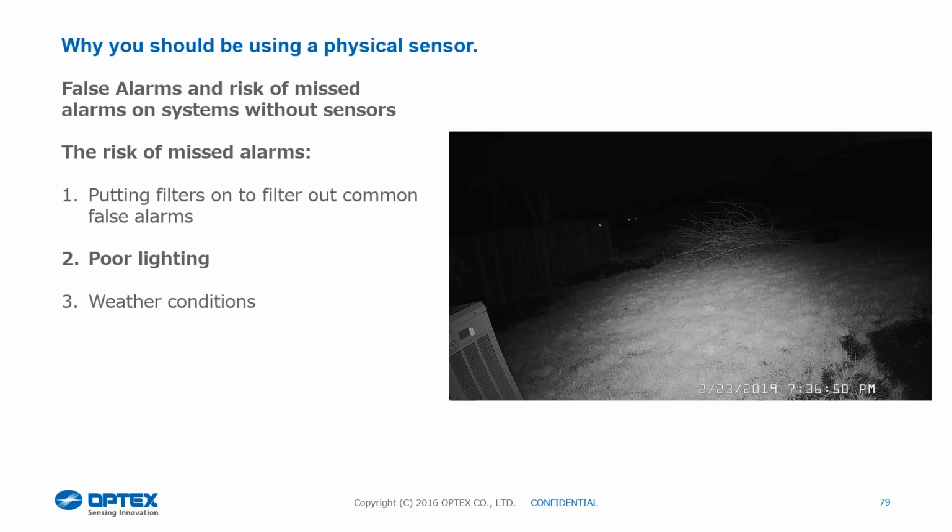Switches into IR illumination, whether that be IR from the camera or an IR light on the CCTV, or sometimes you do get outside lighting sources that are going to actually switch the camera from monochrome back into colour. If that happens and you get a dark contrast in the background, again, chances are you're going to be able to get somebody walking across there without an activation.